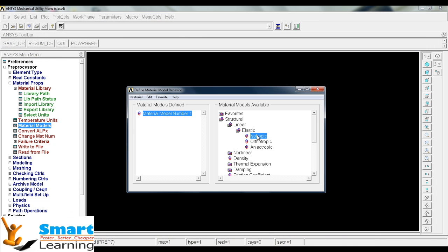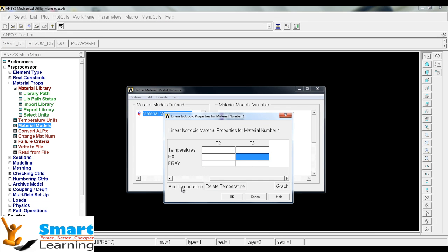If we go to material property and isotropic, I am adding 3-4 materials with a temperature 20, 40, 150, 300, and Poisson's ratio is 0.2, 0.35, 0.24, and it is 0.17, and Young's modulus is, let us say, 200, 250, 300, and it is 400.